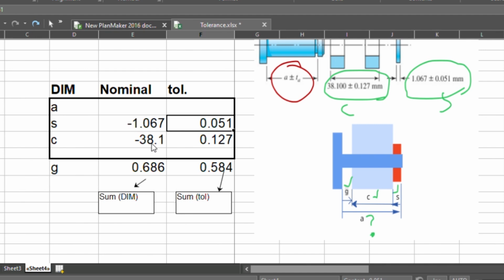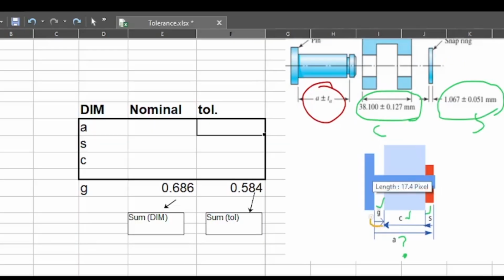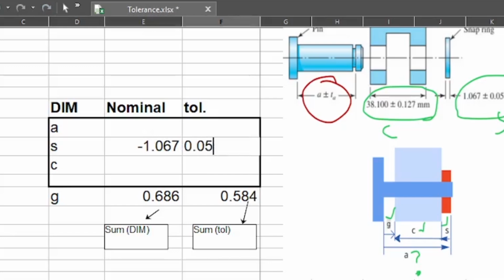So on the sum of all these values with their signs, this is important. The signs are very important to get to the right value. So starting from one side of the gap, if it's in the same direction as your gap definition, it's positive. If it's in the reverse direction, it's negative. So you loop through from point A, you go all the way through the parts and come back, and you aim to get back to point B. Okay, so in this journey, wherever the movement is in the positive or aligns with the AB direction, it's positive. When it's in the opposite direction of A to B, then you give it a negative value.